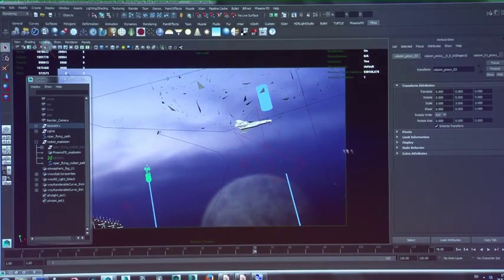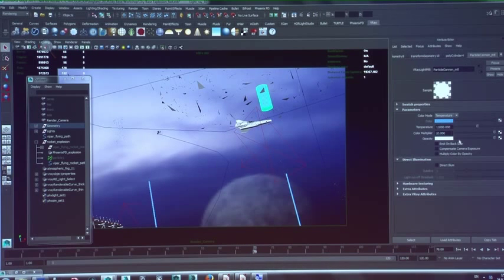Okay, so the next one, speaking about the light material, a really important part about this is, if you take a look at the shader, it gives you control over what color of light you can use. I'm using a physically based approach using temperature in kelvins, which is the method that I prefer, but you can also use just a color. I gave it intensity, and a very important thing in that part is the direct illumination tab here.